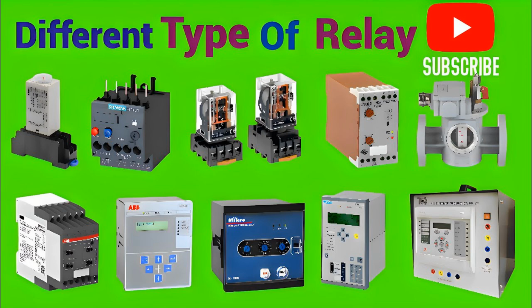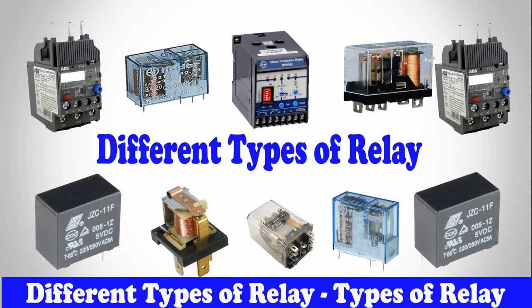Engine control systems. Relays play a role in various engine control systems, such as controlling the operation of fuel injectors, ignition coils, and other components. They help manage the flow of current to these critical engine components, ensuring proper engine performance. In all these applications, relays serve to control high current circuits with lower power signals, providing a safer and more reliable means of operation in automotive systems.